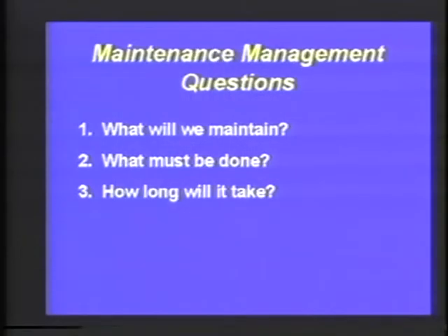How long will it take is a function of the planning process, and that is the labor planning process. But you're going to see in our labor planning process, we actually have 4 major steps. The first step pertains to what we call maintenance work order preparation. And we'll define what preparation is, but currently that pertains to having all of the spare parts, any special tooling, equipment, and documentation that may be required available by the storeroom.